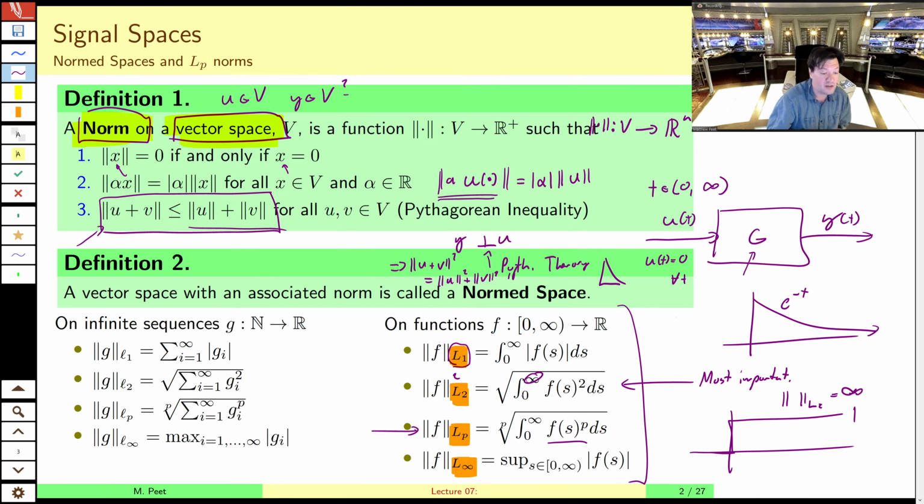Another obvious case where we don't have finite energy is a sinusoid. A simple sinusoid like that goes on forever, never decays. And so we integrate this bit, integrate that. Those are all finite, but we have to keep going forever and ever. And so we keep getting more bumps that we have to integrate. And so ultimately, the L2 norm of that is also infinity, right? So the step function is not in L2, and the sinusoid is also not in L2.